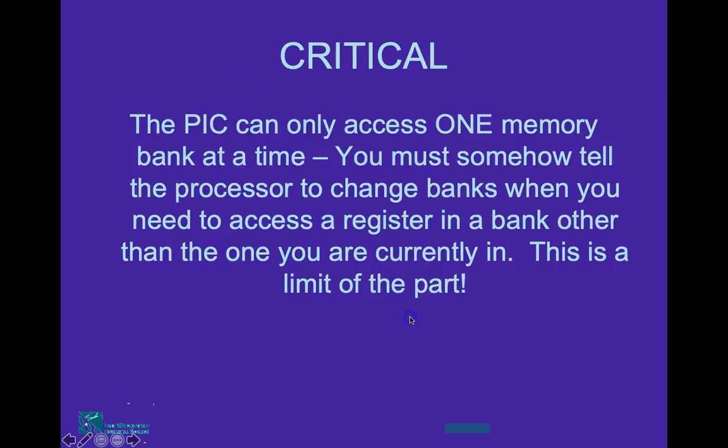Okay, now moving on to the next slide. This slide says that the PIC can only access one memory bank at a time. This is a very critical thing. You have to remember that bank cell can select one bank at a time.